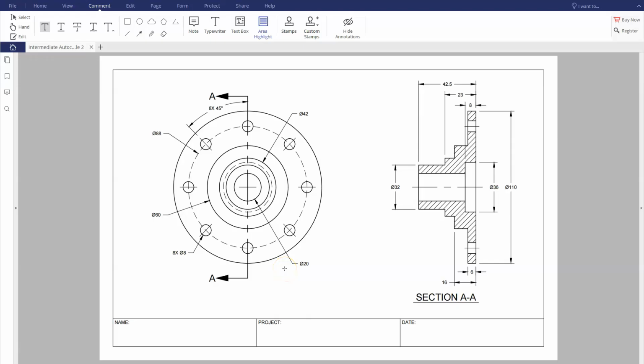Okay, so in this example you see that we have a projection drawing, and what we're going to do here is we're going to also create a section that's going through it. The reason I know it's a section, and in this case it's going to be a full section, is that you can see the phantom line that's running in between it. So in this example we're going to find out how to do hatch patterns. We're going to look at some sections, and we should bring in our title block and adjust it.